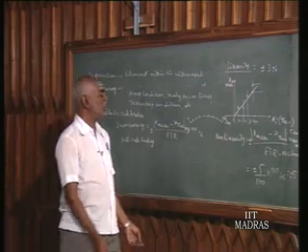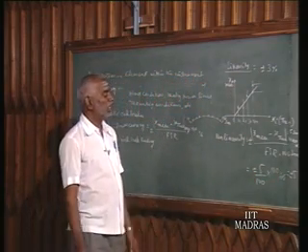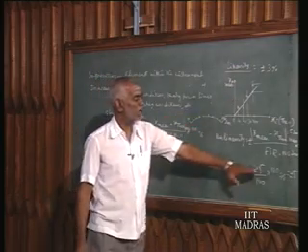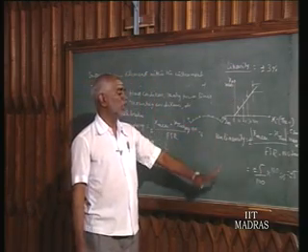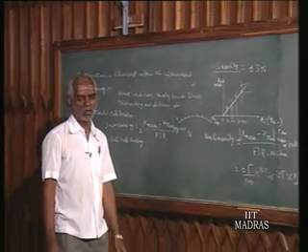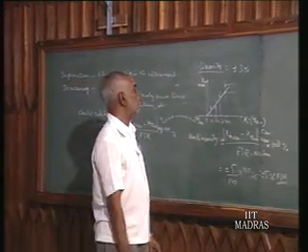And now, when it is given in terms of full scale reading, we have to be careful. We are not supposed to use such an instrument, where the nonlinearity is given in terms of full scale reading, near about the zero point of the instrument. Why is it like that?